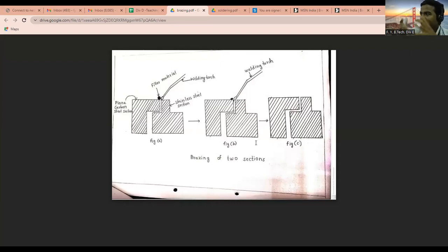Normally in brazing operation we can see in the joining of pipes. You can join the pipes by the brazing operation, or you might have seen the carbide tool, the cutting tools in machinery like lathe machine or drilling machine. The points of the cutting tool, if joined to a tool, look a little yellow in color. That is a brazing.